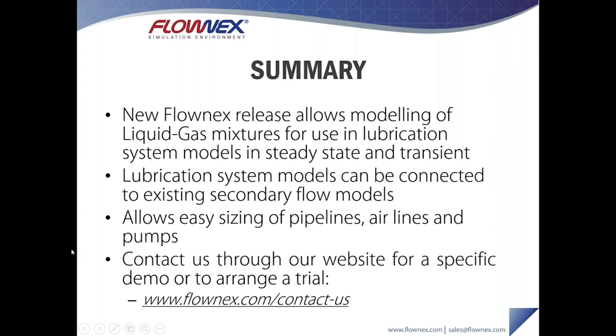With this functionality, it should allow easy sizing of pipelines. This will be our scavenge lines, both from a point of view of determining the required diameter for the desired flow rate, but then also looking at the effect of gravity-fed pipelines and determining whether or not a scavenge pump will be necessary. We can then also look ahead at sizing airlines to ensure that we have pressure balance inside of our bearing cavities, and then also sizing pumps as well.